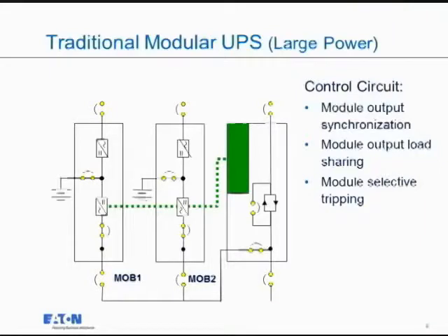Well, I want them to evenly share the load. So what I used to do before, and the easy way, is I simply tell these 2 inverters, hey, I don't care how you operate, but the control module over here, a system level control module, will tell them how to operate. What's my single point of failure in this system? The control module. So regardless of how reliable, how much money I spend, how much MTBFs I do on the power components, my reliability comes down to the reliability of a printed circuit board or a motherboard.